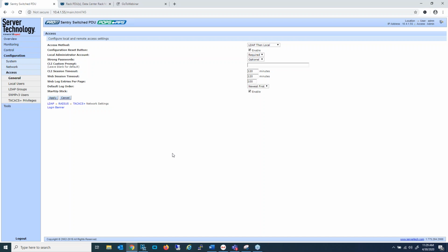And I do have the formula. If you want to contact me after this session, I can send you the actual formula that we use for determining the percentage of out of balance. But those are the two choices: either disable the notification or change that percentage from 20%, the default, to something greater, or ideally attempt to reorganize where things are plugged in to actually achieve better balancing.